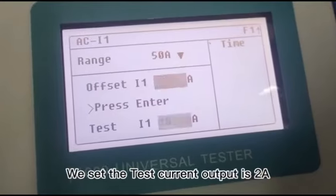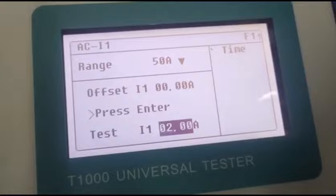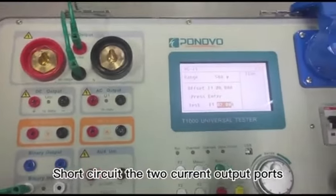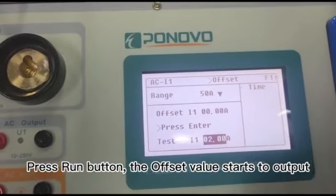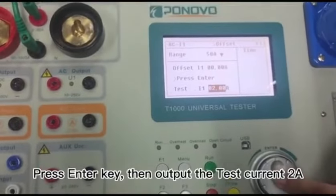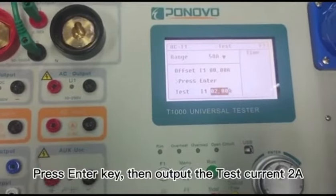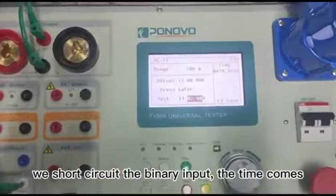We set the test current output is 2 amperes. Short circuit the two current output ports. Press Run button, the offset value starts to output. Press Enter key, then output the test current 2 amperes. We short circuit the binary input, the time comes.